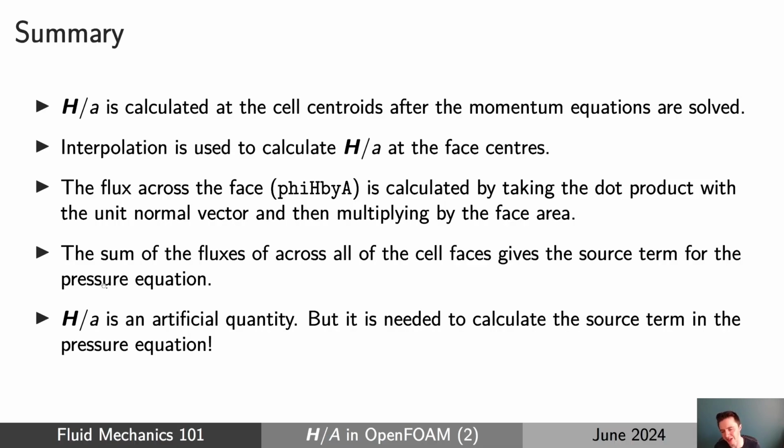And you'll remember that HbyA is an artificial quantity. It doesn't really have a real meaning. It's not a real field. But the reason we introduce it is so that we can calculate and evaluate this source term for the pressure equation. It's an intermediate field that we have to calculate if we want to assemble and solve the pressure equation in this form.